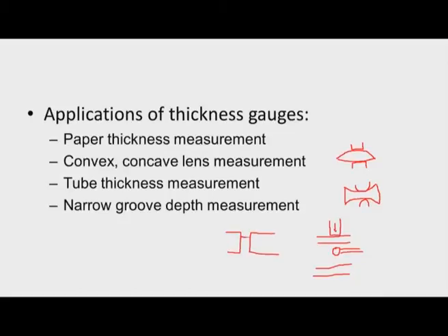In such cases we have to use a blade type plunger and anvil, which will comfortably go into the narrow groove. Blade type plungers and anvils are available with thickness of 0.75 millimeter, 1 millimeter, 1.5 millimeter and so on. So, appropriate blades we have to select and can be used for thickness measurement.